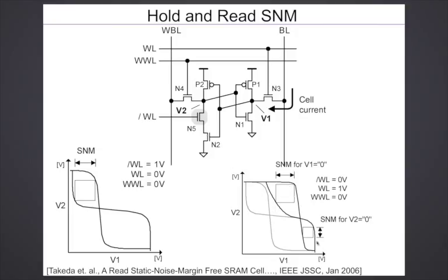So if I didn't shift it to the right, this is the DC transfer curve of this inverter. If I kept the old value, then you see that I have lost the noise margin. There's no noise margin here. But because I have put the series one, now this graph is also telling me that I pulled it out and I have a noise margin now here, some positive noise margin.